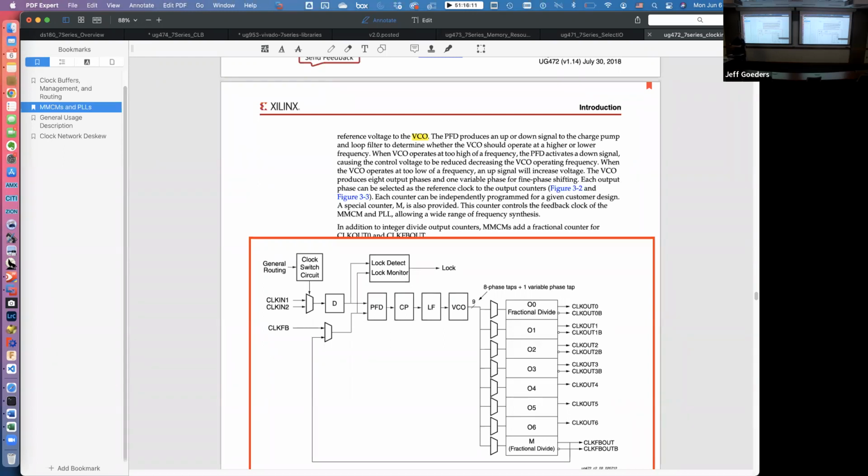Just a few comments: for the clock wizard, you can also do a manual override, so you can play around with the different dividers and multipliers. Exactly. It calculates it all for you, which is kind of nice. Very nice. And also in Vivado, there is a language template in the flow navigator near the top. You can search any primitive and it will show you how to implement it. Okay. I've never used that button. I always go to the document I showed you and copy and paste their Verilog.